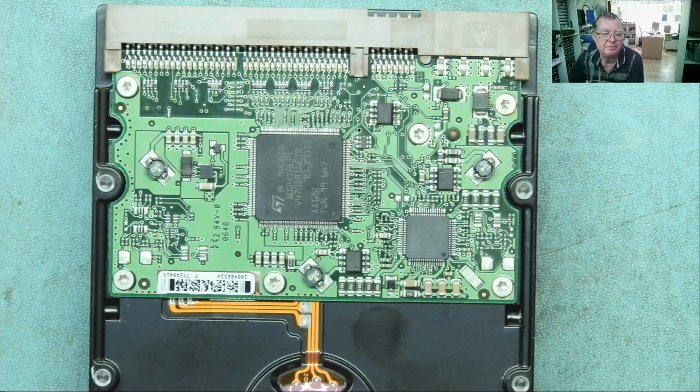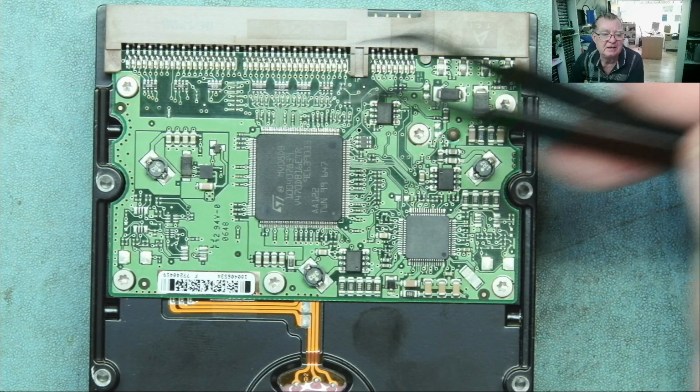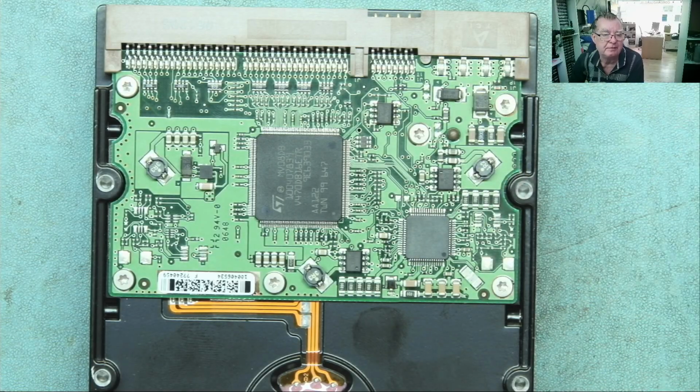So to sum up, the thermistor or NTC should read a relatively low resistance. The TVS diodes and the MOV or varistor should read open with your multimeter. They are protection devices. When they fail, they go short, apart from the thermistor which goes open. If you have blown MOVs, blown TVS diodes, probably just replacing it will work as long as you have got rid of the external voltage surge or incorrect wiring. They're there to protect everything else rather than cause other components to fail.